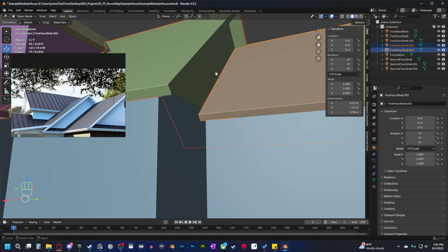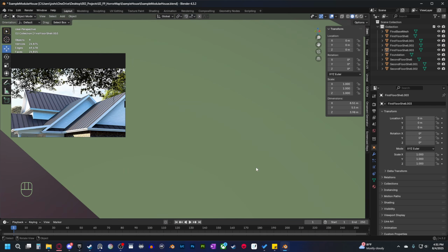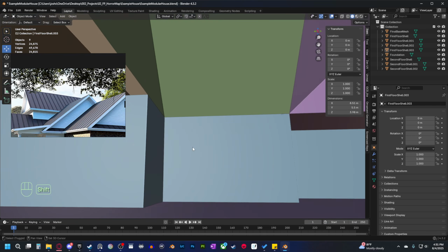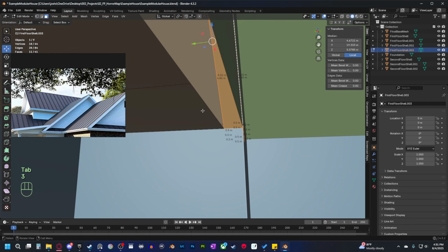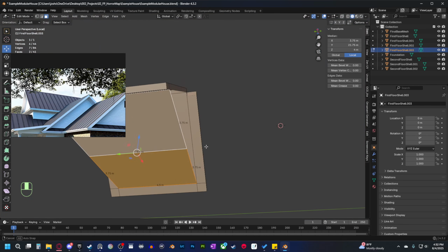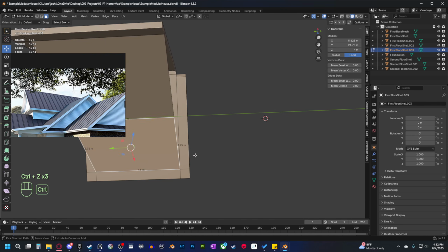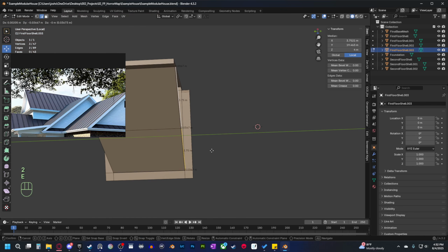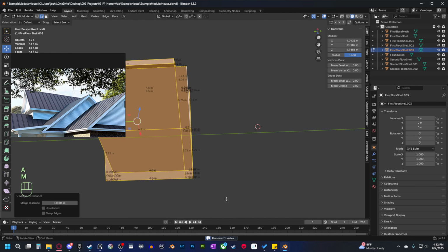So now this wall lines up with our back wall perfectly, and I like that better. And then what we'll probably want to do is extrude maybe this piece on Y. Oh, hold on. I meant to extrude just that edge on Y by 0.5 or minus 0.5. Okay, and then I'm just going to merge vertices.